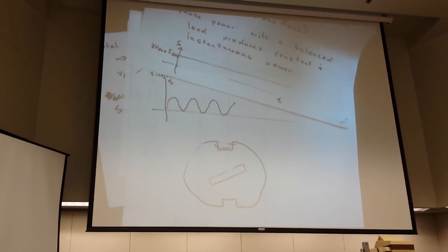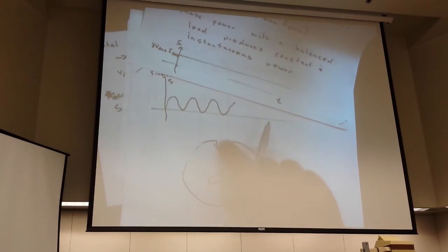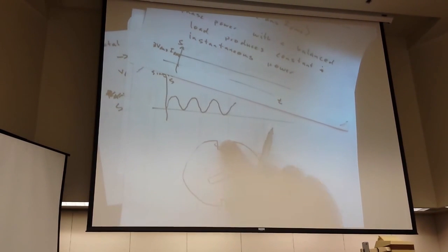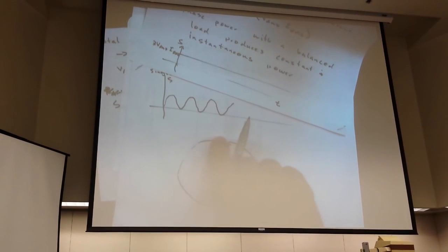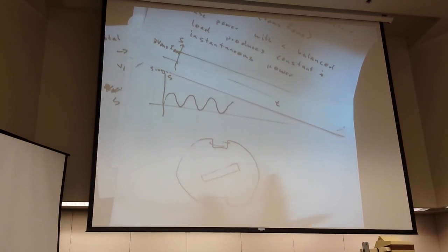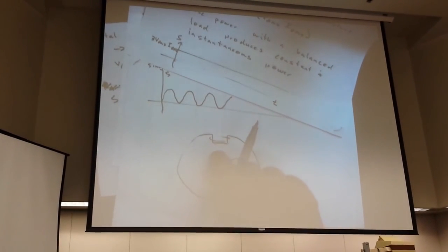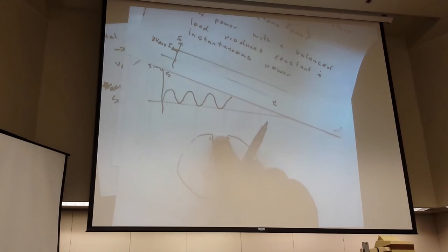But this needs to keep spinning. If I have this as a constant, what happens? Well, it goes and lines up and eventually it just settles there. So that's the whole point of AC: you magnetize this, the iron lines up, but as it gets closer, the AC field drops to 0, the magnetic field drops to 0, it flies past, you reverse the magnetization, and it keeps going around in a circle, and thus we have motion.